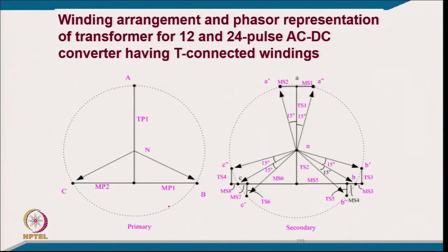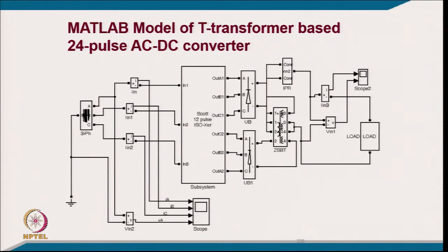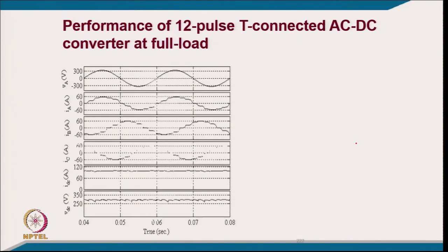Okay, you have one horizontal and vertical, that is the typical. The neutral you do not need, but here you require the neutral just to equalize the voltage, and this is how you are getting a phase shift. Typically for 12 pulse, a 30 degree phase shift, with plus minus 15 degree for one set of winding, another set, another. So, you have one three phase and another side another three phase. And this is typically the total system model, and this is the transformer connection model.